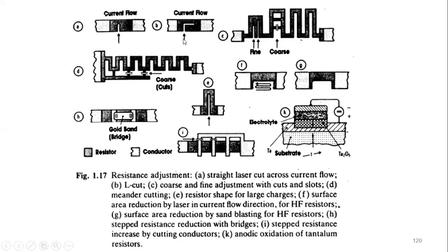And here you can have the L shape cut, and it depends on whether your resistor value is high or low; accordingly we can have this cut. To adjust the value, this is the fine tuning method. So these tuning methods can be used while doing the design of your project on the PCB. This is required. If you have a track with high resistance, you can do this cut and accordingly the resistance can be adjusted.